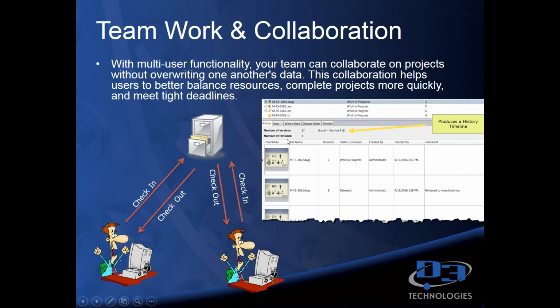That goes back to your workflow. If version 4 got put to revision C, then that's controlled. At the end of the project, we can purge these files, and it would reduce these versions down to the controlled ones. First version, last version, and anything that produces a revision change. So that if you're going to archive this drawing for later, you don't need to keep every time Joe checked it in, but you do want to keep the controlled ones.